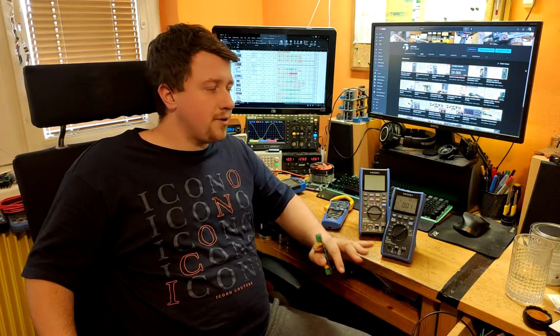So, to sum it up, I hope you understood the absolute base of FFT. So now you know some ground basics, really ground basics, how AC circuitry works. Therefore, I hope you understand the principle of evaluating THD. Why does it cause problems? Mainly to capacitive loads, but also network sensitive devices. You also know what multimeter can be used to quickly determine THD in the field.